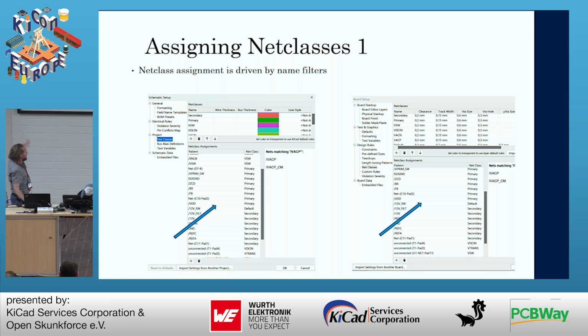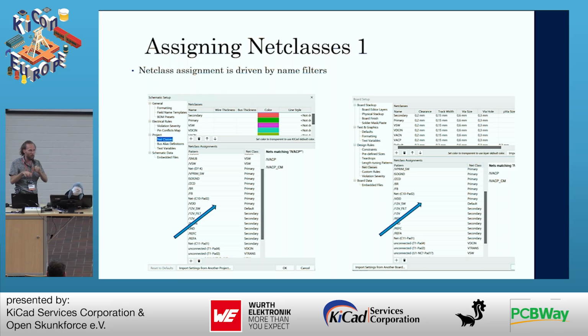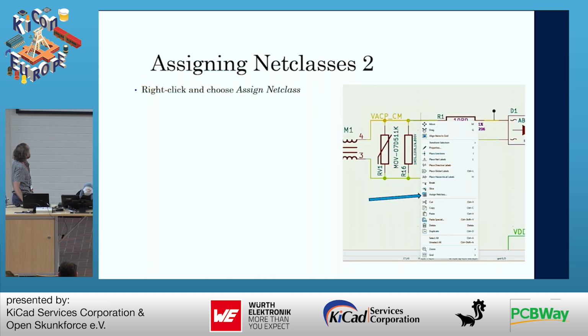But yeah, you create the pattern. That's one way. I will explain another way. But you could sit there and type in all the names of your nets and then associate the net class with those nets. And then eventually you will have all your nets in specific net classes.